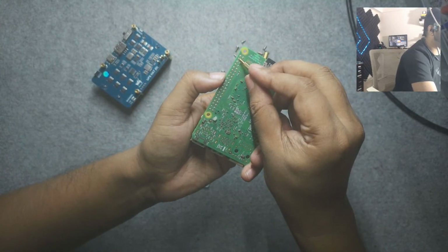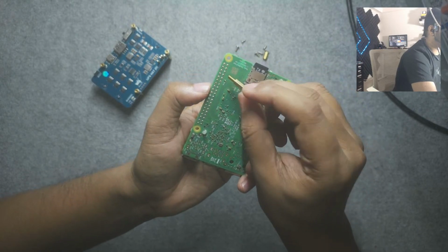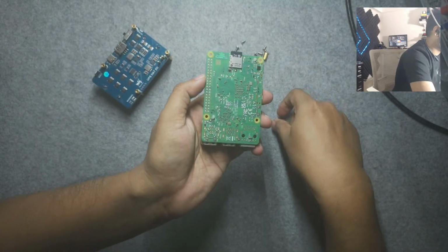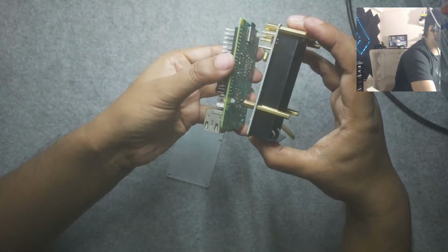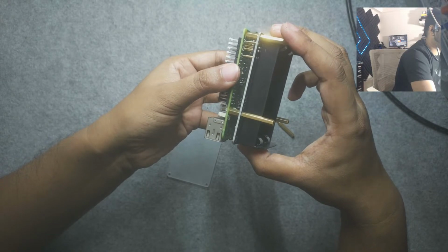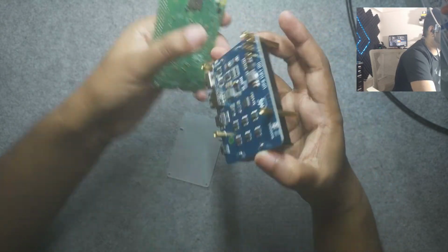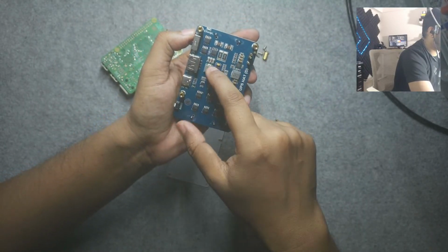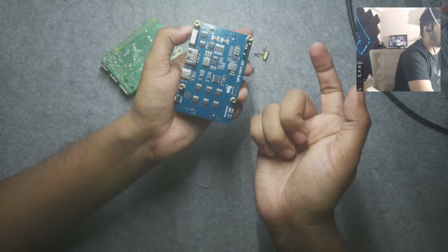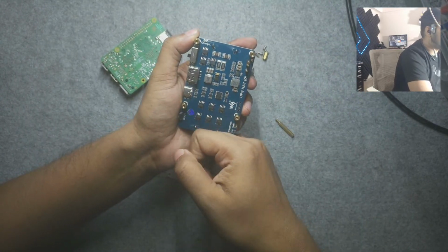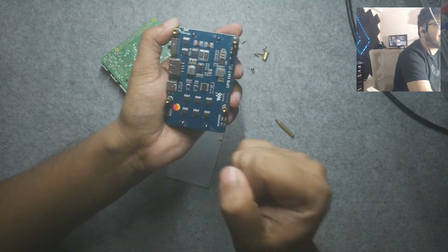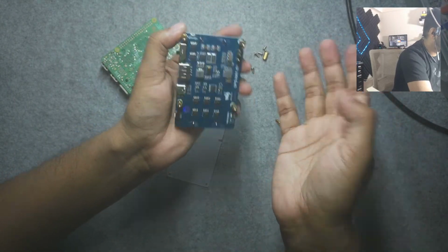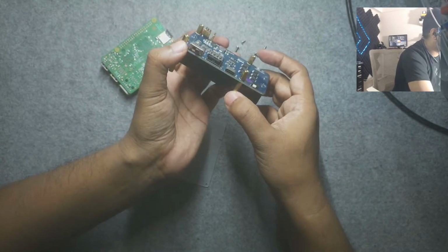So here's a 5 volt and ground, as well as the I2C line over here, which is what these ones connect with when we put it here. Through which the battery management IC can actually send back details to the Raspberry Pi saying what the battery status is, so you can monitor it much more easily, which is very handy.